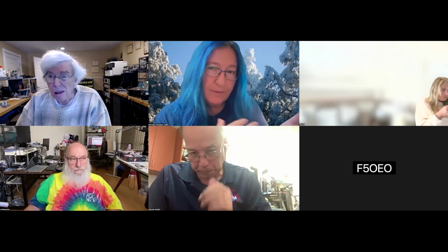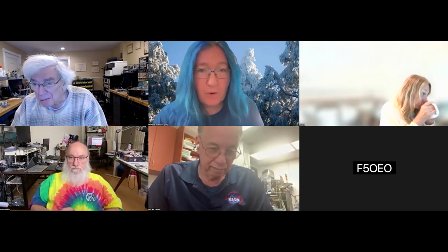We say, what's the bandwidth, what's the power, what's the modulation index, and so on, and you get that set of statistics. And then you just do a table lookup and you say it's probably BPSK and it's probably this digital format. So I'm going to guess that that's probably what we're going to do. If we have to do something fancier than that, then we become very power limited because we have half a watt for the whole thing.